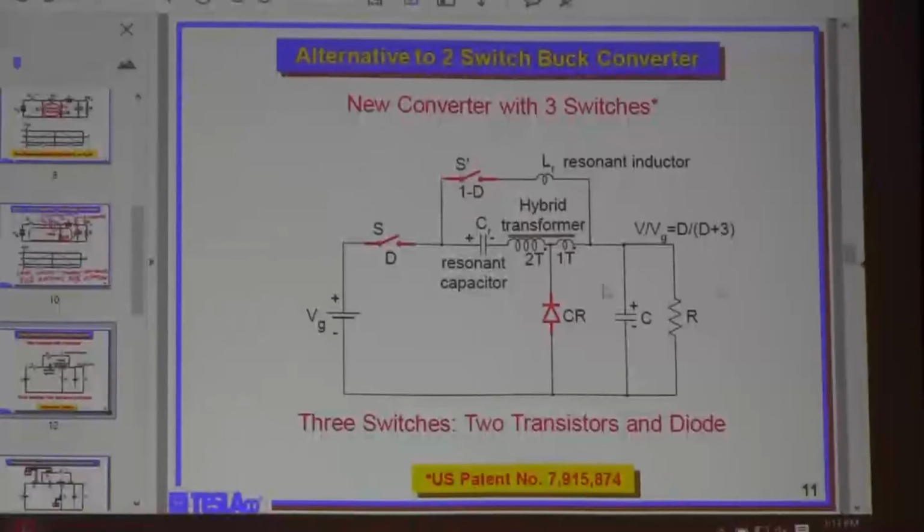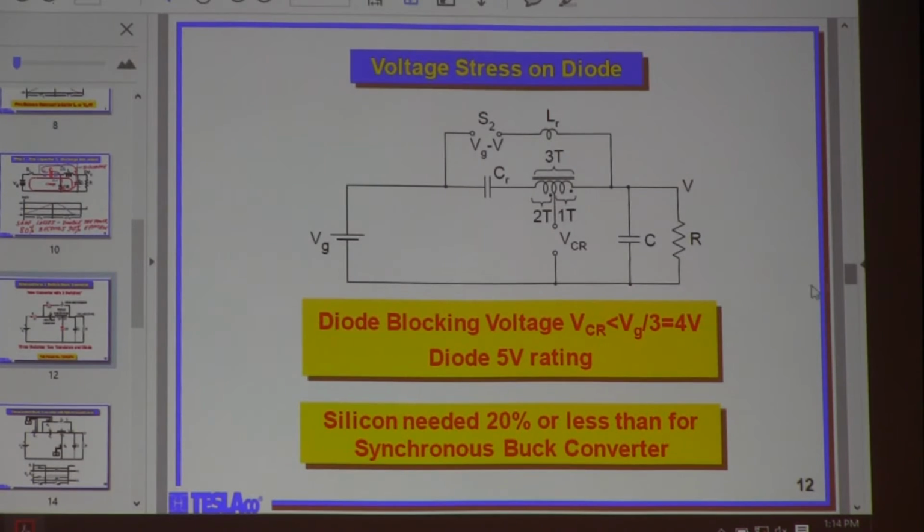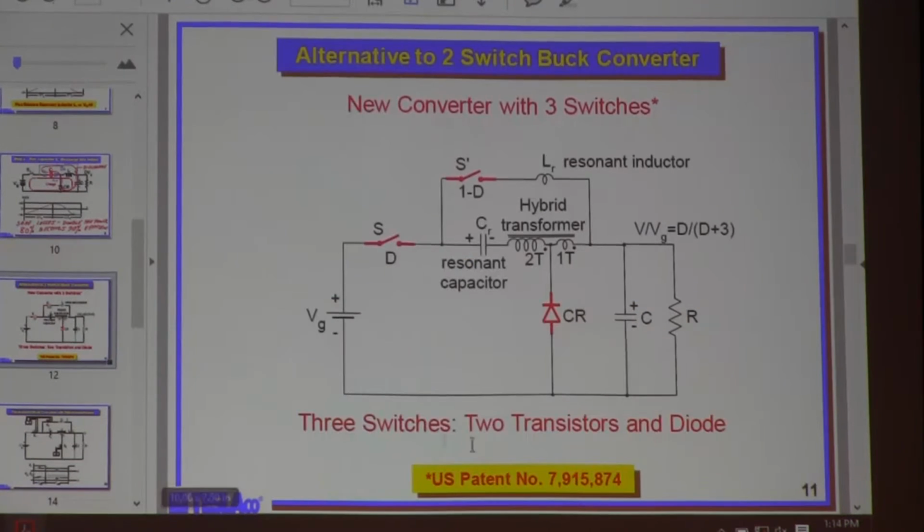And that was one with the resonant transformer, which you cut off. So I will actually not go into much detail. Blocking voltage. Yeah, let's go to this one here, original. If the turns ratio is 10-to-1, for example, what is the voltage that this diode sees? At 50% duty ratio, the diode sees twice the output voltage. So if output voltage is 1 volt, the diode is rated for 2 volts.